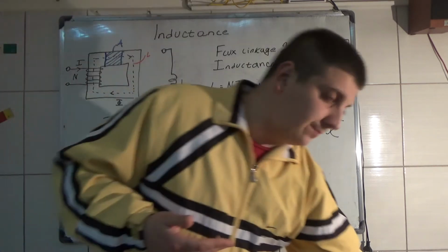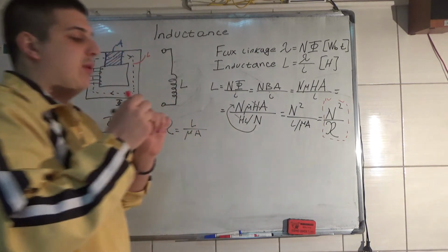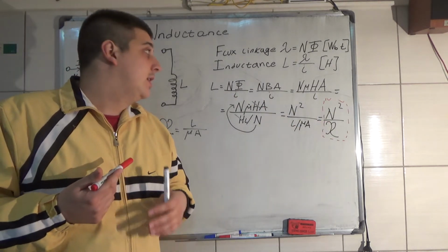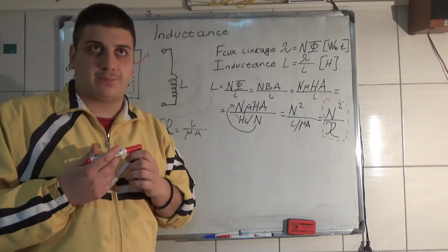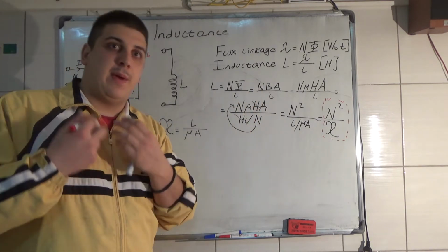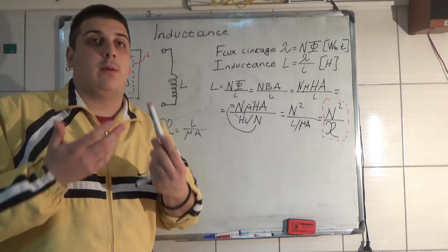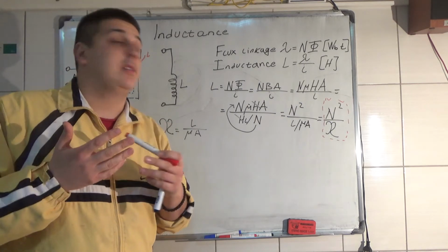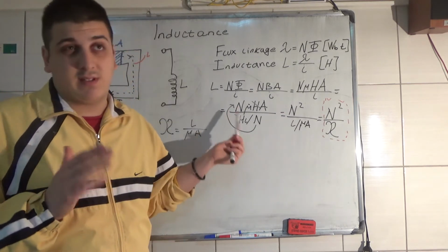For me particularly, this is one of the most important formulas. And as you can see, reluctance varies and the number of turns also varies. So L, the inductance, isn't a constant. It can vary a lot because the BH characteristic, the magnetization curve, is not linear when you have real magnetic materials. There are saturations, there is hysteresis, and you have some limits to this. But usually the reluctance stays about the same.